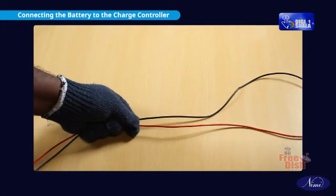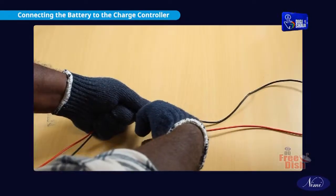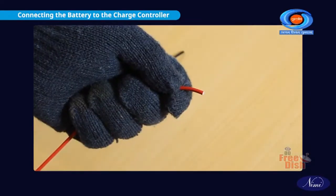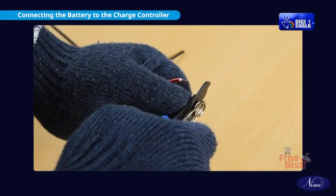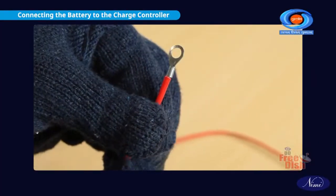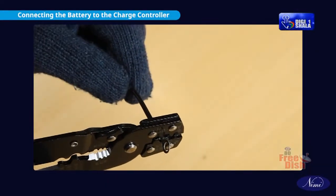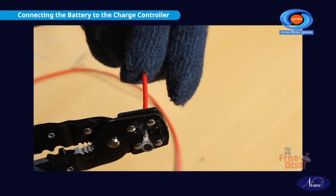Measure and cut two lengths of electrical wire required to connect the battery to the charge controller and the circuit breaker. Remove the insulation sleeve at both ends for 12 mm and insert the conductor into cable lug terminals as shown. Use the crimping tool with the correct slot. Crimp the lugs on one end only of both wires.